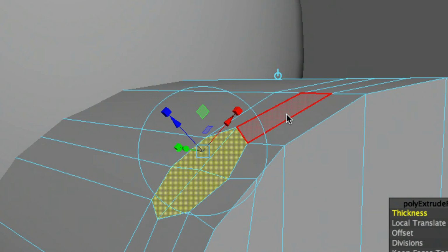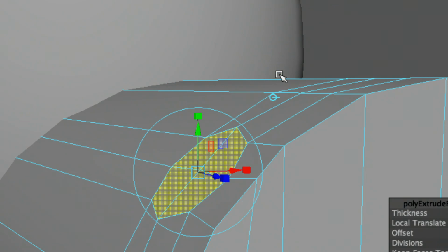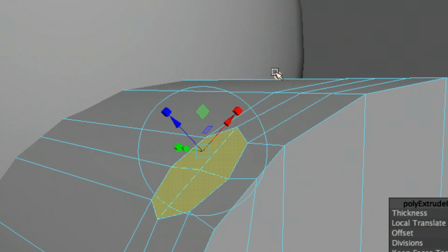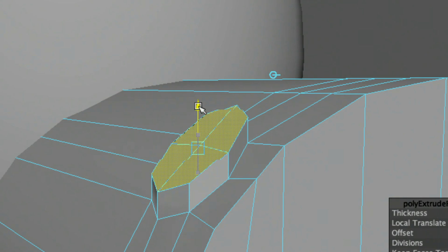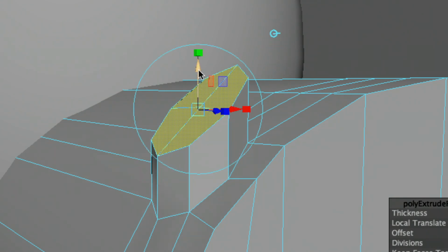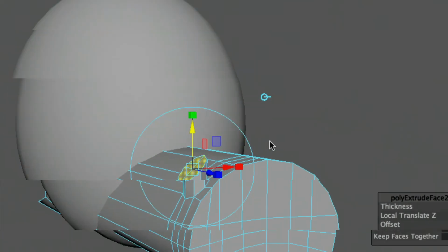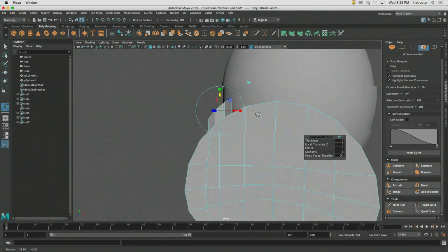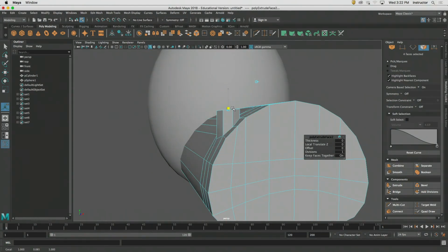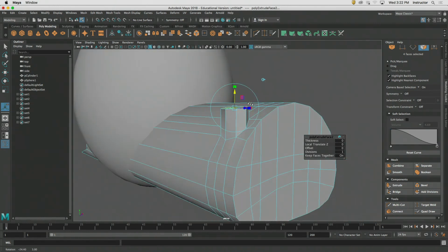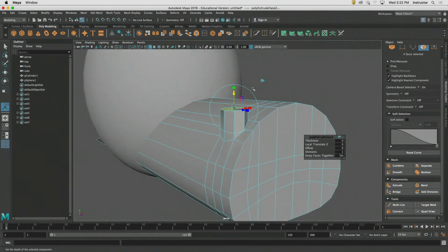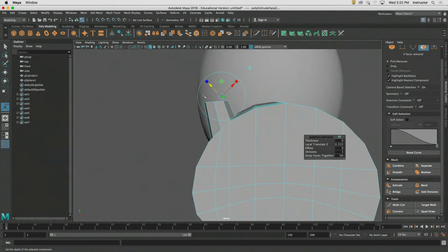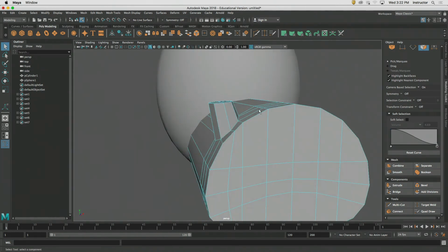But if I wanted to pull these perfectly straight up and orient my tool handles to the global understanding of the XYZ axis, that's what that switch does, that little blue circle. Local, now we're in local mode. This is global. Different result, okay? Even squish it down, you're on your way. I think given the context of what I'm doing, it makes sense that it be the other way around, okay? But that's a good thing to keep in mind.